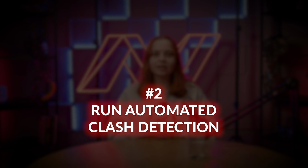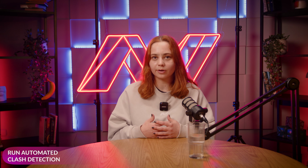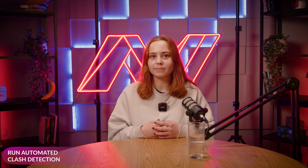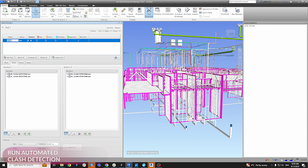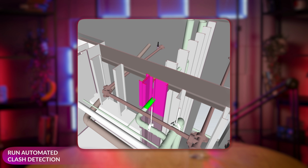Second tip, run automated clash detection. Utilize automated clash detection tools to identify spatial conflicts between different building elements. Run clash detection software like Navisworks, which automatically checks the BIM model for any conflicts between elements. For example, the plumbing model might have pipes running through a load-bearing wall. This can ensure compliance with standards at every stage.